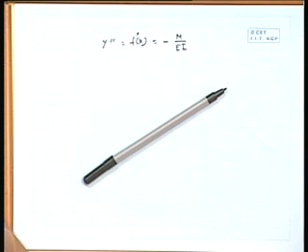So, first slope is the first derivative, and the second derivative is basically the curvature. That curvature will be equal to the bending moment divided by EI. The EI term we have already defined; it is basically the flexural rigidity of the beam. M is the moment, and that expression is very important.